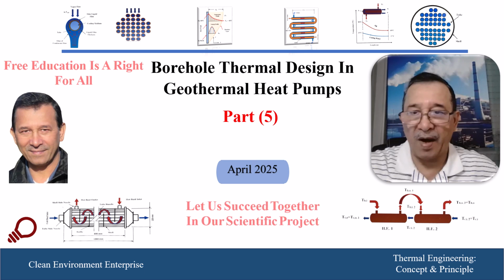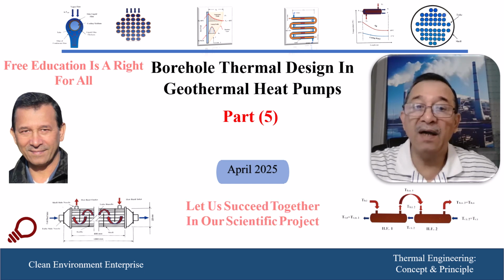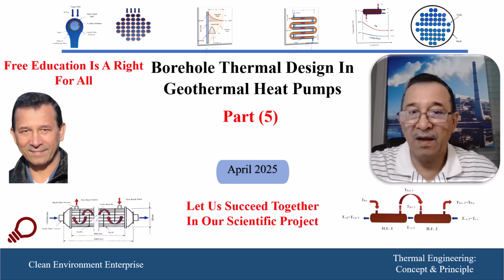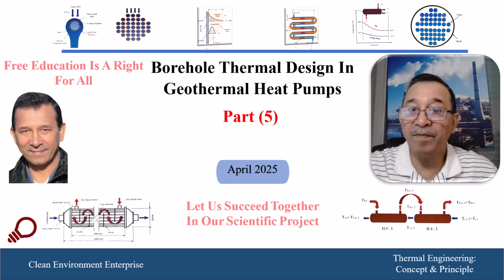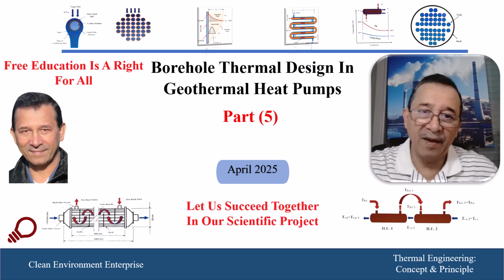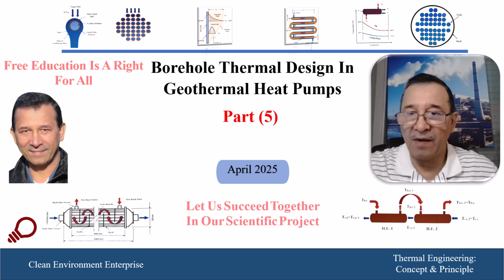In this part, I will cover the construction of the heat pump itself and the borehole and how we can estimate the depth of the U-tube in the ground, which is related to the properties of the geological aspect for the ground and the thermal properties of the grout or filling that is surrounding the U-tube in the ground.